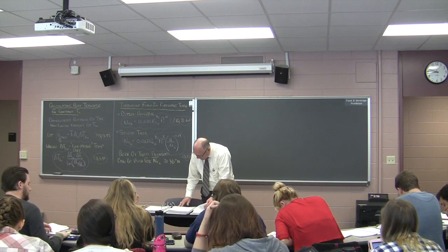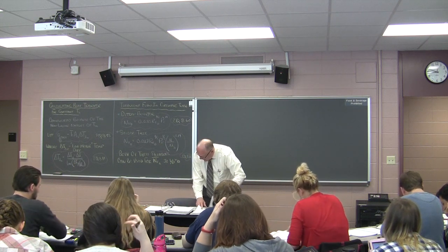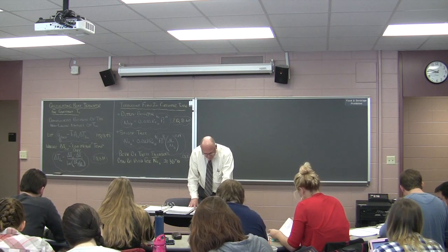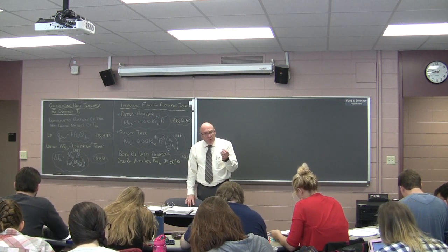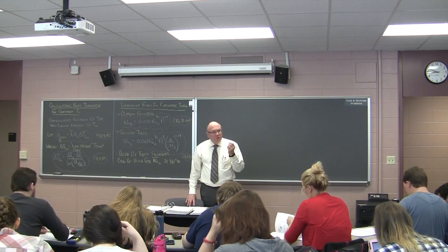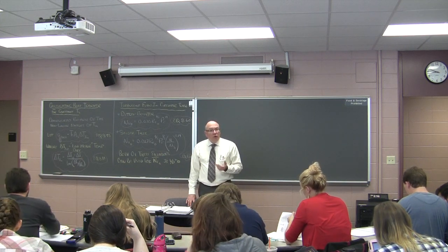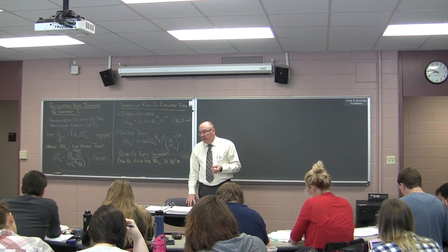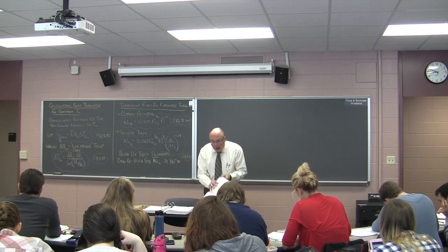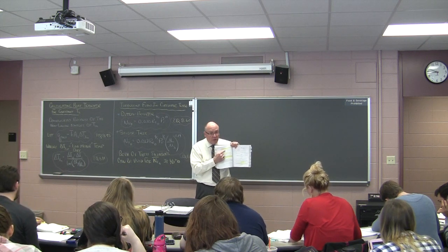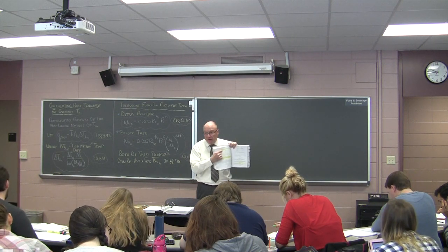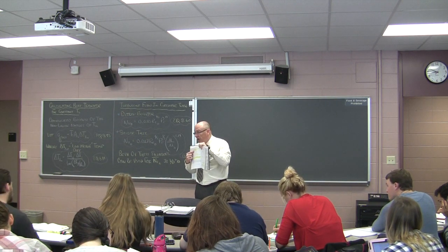And the last thing I want to point out is equation 8.6 and 8.66. 8.6 is a very useful equation. It's at the top of the page, on page 492, and is the Reynolds number expressed in terms of m dot. It's a quicker way of solving the Reynolds number than having to solve for the mean velocity. Okay? This is an equation that's worth being highlighted and underlined in red because it's one you should use a lot. Okay? The Reynolds number expressed in terms of m dot. A valuable equation to use when you're solving these problems.